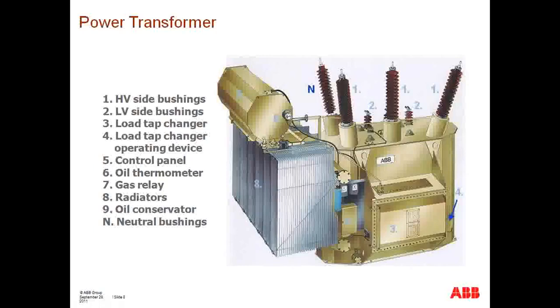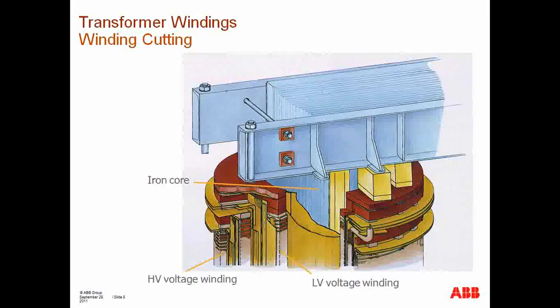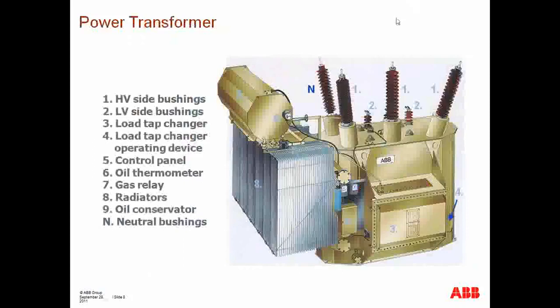And it's smaller because you need a smaller creepage distance because the voltage is less, thus you don't need as much insulation strength, since the voltage of the line is smaller. Here, a couple of other components that are important to mention.